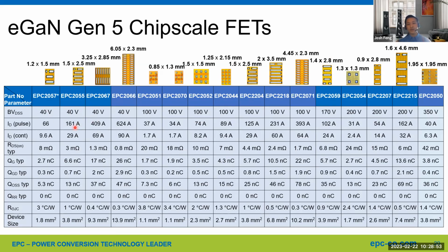If you need to go up to 36 volts or 48 volts, the Generation 5 100-volt device, maybe in this type of category, less than 10 milliohm device, will be something a little more attractive. And if you have to implement some type of synchronous rectification, which we didn't touch too much here, the popular choice will probably be, for example, 150-volt, 170-volt device or up.